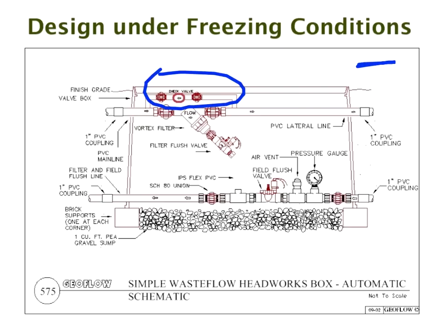If you don't have that extra spring check, then of course it will flow back into the filter and block here, and then the supply line will freeze. So that's a very simple way to get around that without any extra electrical connections.